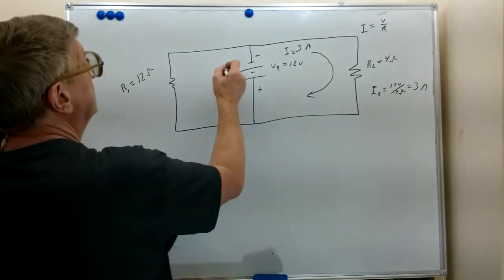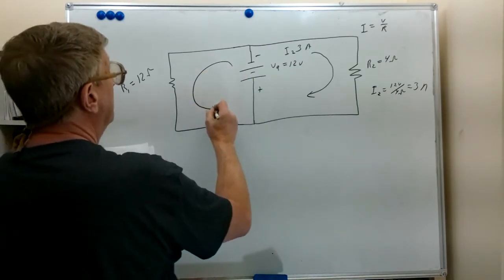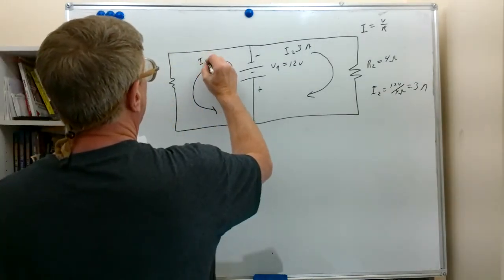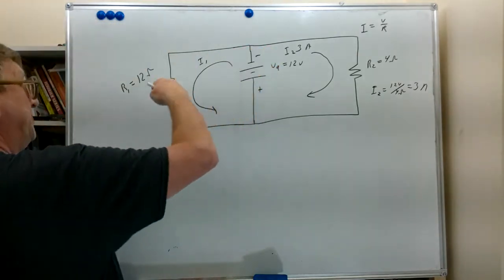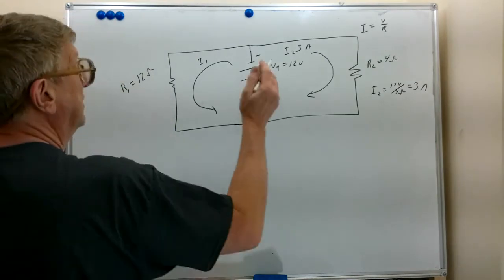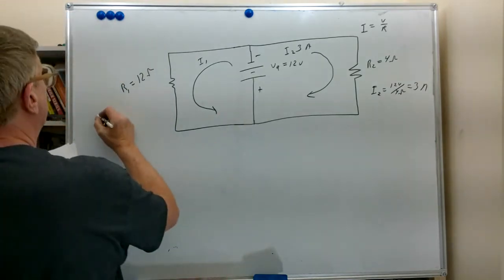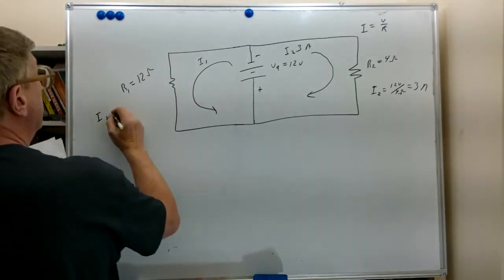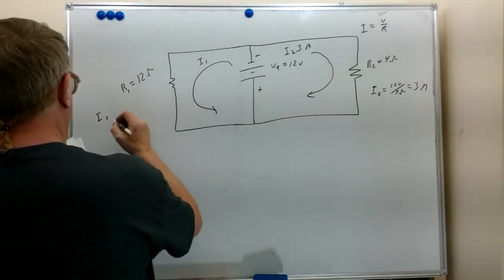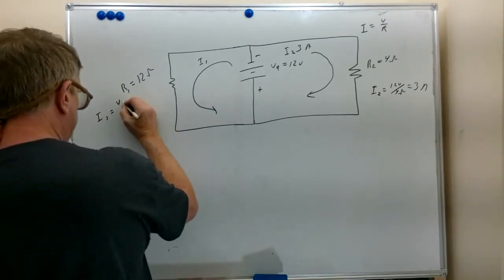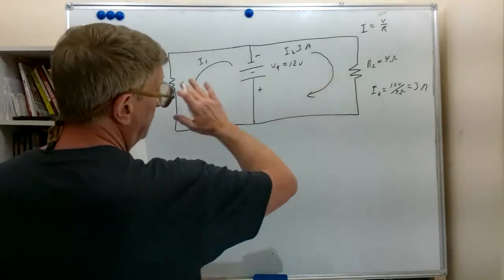So we'll calculate I1 now in the branch containing resistor 1. And you see that it does go negative to positive. We'll use the same I equals voltage divided by resistance. So now we're calculating I1, that was I2 that we did first, pardon my mistake there, is equal to the voltage applied again, because the voltage applied didn't change.